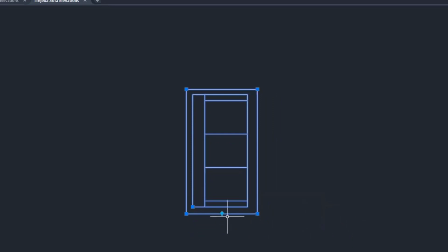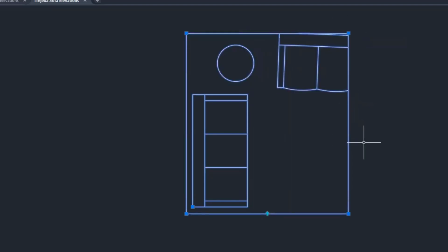I can take that rectangular area and invert it by simply clicking on this arrow, invert this X clip boundary. So I can click, and now it's going to show me, or at least it's supposed to show me the opposite, but it didn't quite do that. And we don't normally use that invert. I usually leave it alone. But I want to show you something else that's interesting here is I can take this clip and now I can pick one of these corners and actually drag it up and drag it over and control the extent of that clip.